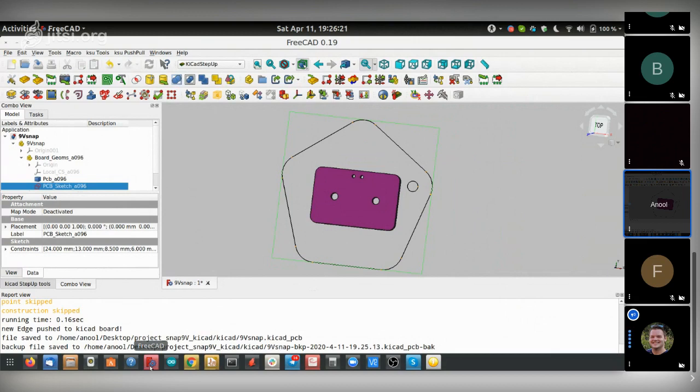Right. For construction lines in FreeCAD, if there were some of those construction lines that we wanted to carry over into KiCad, let's say in the drawings user layer, is there a way to export to a specific layer, or should we just export it as outline and then in KiCad change the specific outlines back to whatever layer that we want? I think I'd go with the latter option.